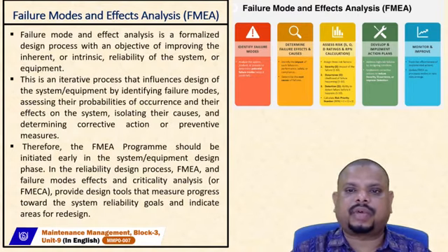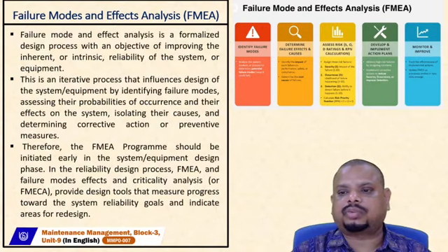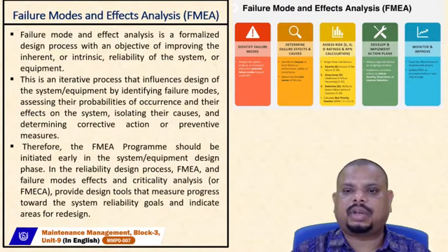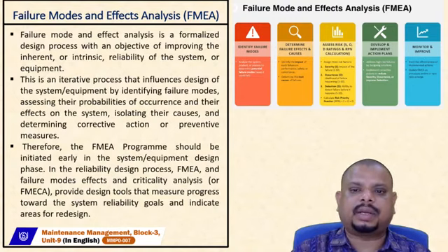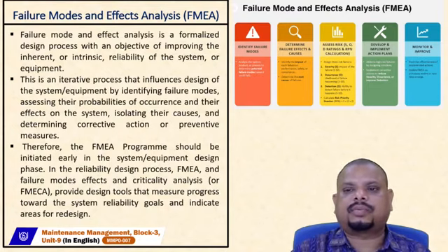The last step of your failure mode analysis is monitor and improve. That means under this step, you have to continuously track the effectiveness of implemented actions and update the failure mode effect analysis as the process evolves or new risks emerge. So these are the 5 steps used under failure mode effect analysis. I repeat: identify the failure modes, determine the failure effect and causes, assess the SOD ratings and RPN calculations, step number 4, develop and implement the action plan, step number 5, monitor and improve.